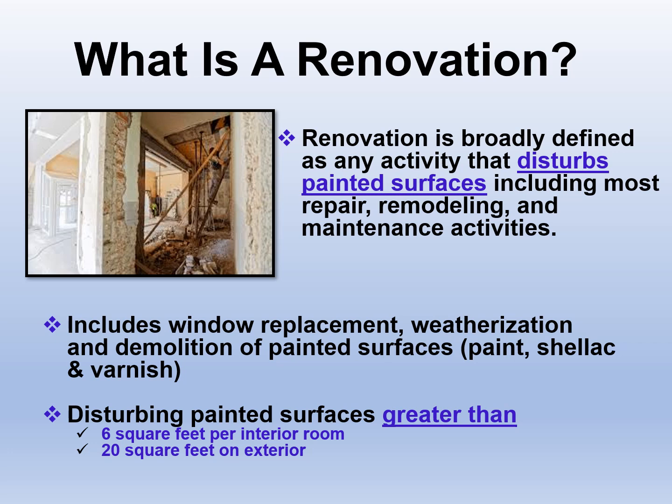And that will include regulating the area, putting down the appropriate poly, using lead safe work practices, wet methods, HEPA vacuum, all those things will come into play at this particular point.